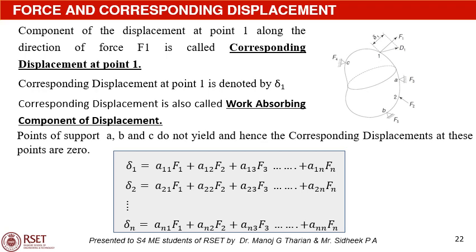Likewise, the corresponding displacement at point n is given by delta n equal to An1 F1 plus An2 F2 plus An3 F3 plus etc. plus Ann Fn.